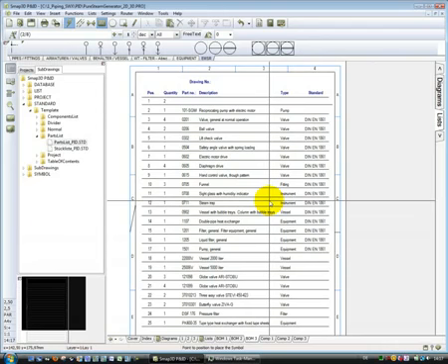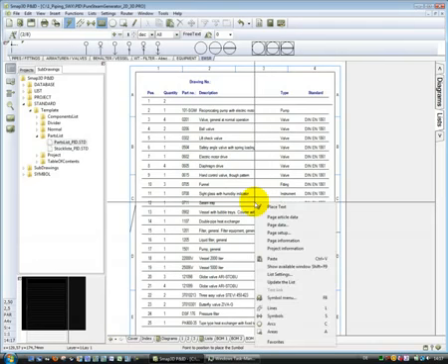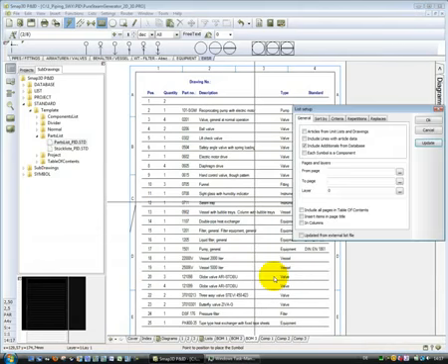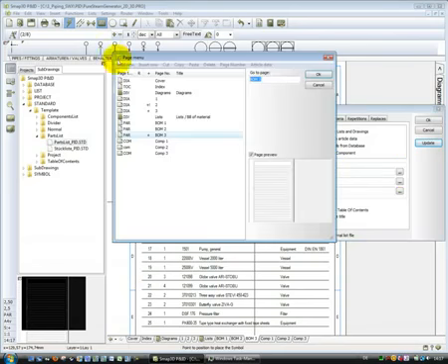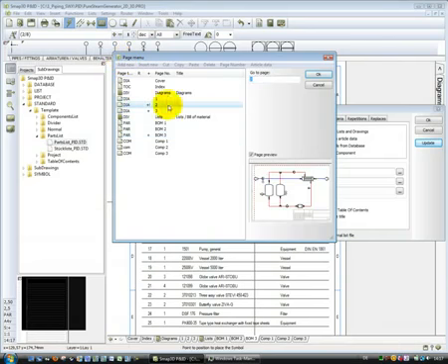If this is too much because I just want to evaluate, for example, diagram number 2, then I have the possibility to change this. With the list settings I have access to all criteria and information where I can control the list. If I just want to include page 2 in my list, I can select from my page menu just diagram 2, the diagram I enhanced minutes before.